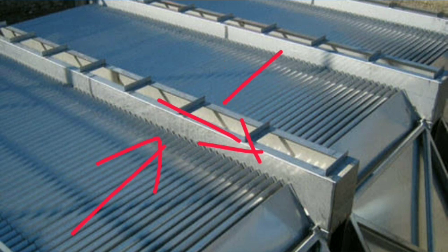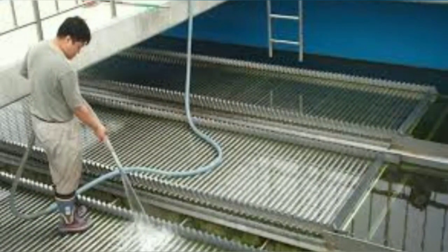And here in this case, the flow passes from the bottom by using small inlet orifices, and it rises up to the settling zone and proceeds upwards through the plates. As it rises upwards, since only the water can rise up against gravity, the particles cannot rise up. They settle down in the settling zone itself.